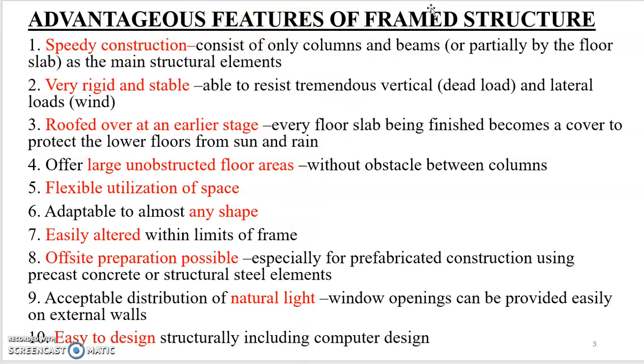First one, it is a speedy construction. That is, we can make these frame structures in a very short time by constructing columns and beams. And the second one, it is very rigid and stable. That is, these frame structures can resist heavy load and wind loads which may act on them.